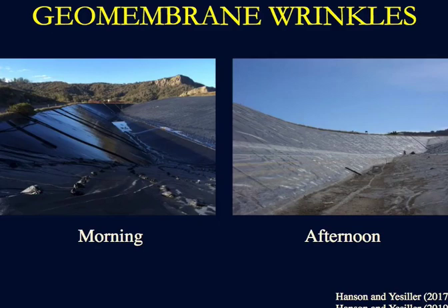The difference in membrane behavior between a morning session or nighttime and daytime was significant. You see an image here, a photograph. By the way, both of these images are looking toward that corner that I highlighted in the overhead view. We see in the morning that membrane is tight as a drum. And in the afternoon, due to the sun exposure and increase in temperature and thermal expansion of that product, wrinkles are formed. And again, these are of significant height.